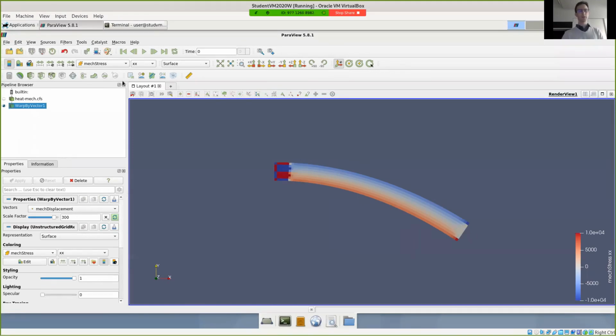If we also look at the range of stress values, so we rescale our analysis, we can see that we have very high stress concentrations here at the corners where we have applied the fixed support, which shows us the phenomenon that these artificially created very high stresses from the boundary conditions can have a significant impact on our analysis. So in fact, we should choose a bit more realistic boundary conditions here if this was the main target of the analysis.